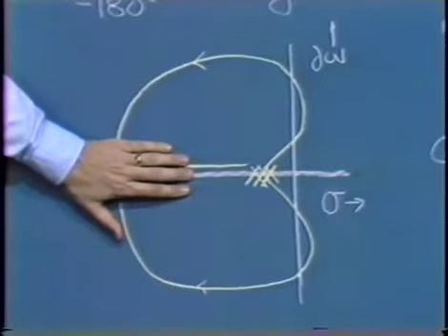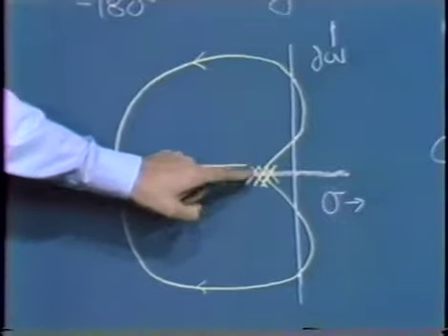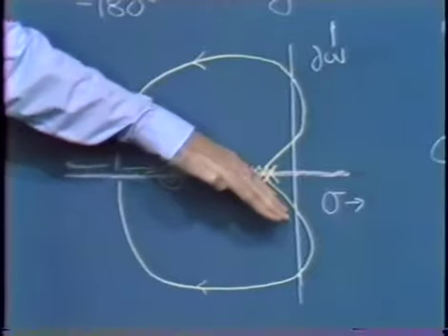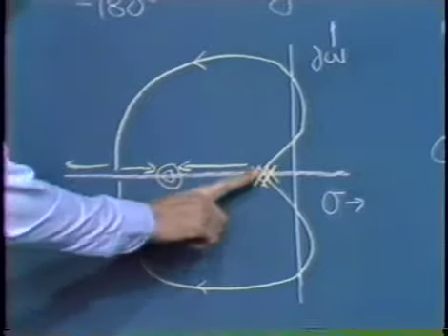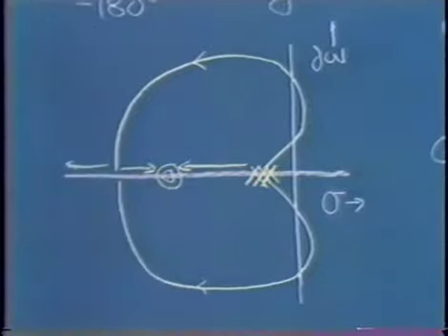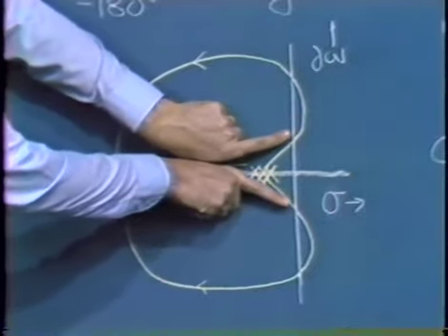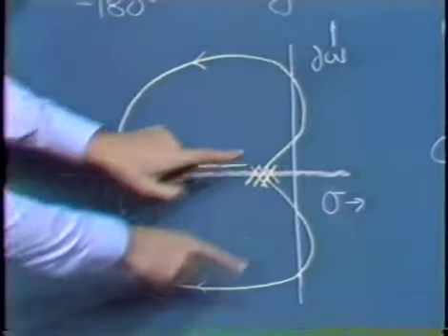Initially, we should be able to ignore the 2 zeros, their high-frequency singularities being further away from the origin. And so we'd anticipate that this triplet of poles would give us the usual plus 60 degrees, minus 60 degrees, 180 degree branches in the s-plane. And again, depending on the relative spacing of the poles and the zeros, it's very possible that for some range of the A naught F naught product, there are 2 branches in the right half plane.